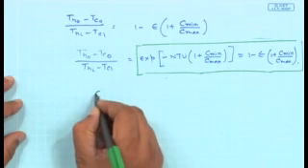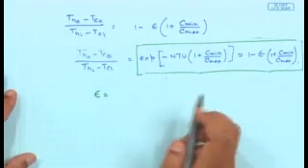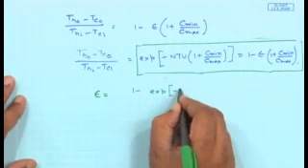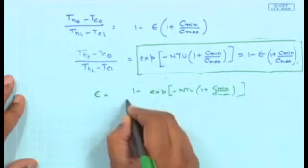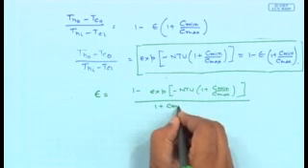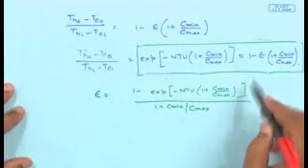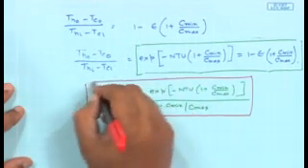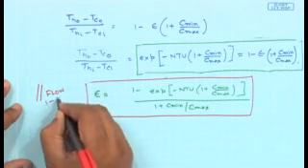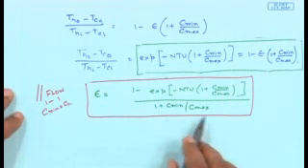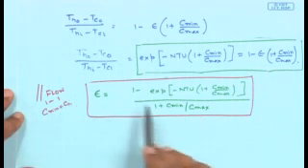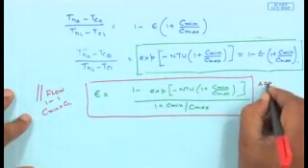So this is the simplest possible form of the epsilon-NTU relation, and I will just simply complete this to give you an idea of what the final form of epsilon is going to be. So epsilon from here would be equal to 1 minus exponential of minus NTU times 1 plus C minimum by C maximum, divided by 1 plus C minimum by C maximum. So this relation one can derive for the case of parallel flow 1-1 and C minimum equal to CH. The same result can also be obtained for the case when C minimum is CC.